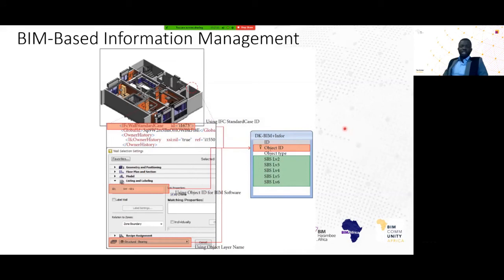The management is achieved by connecting individual information that is being generated here to the individual objects in the BIM model. The construction information database is linked to the BIM model using the space-based categorization codes, which have been generated. Equally, the BIM model object allocated to each categorization code is stored on the database to ensure synchronization, such that we can use the objects on the BIM model to retrieve the information that was carried out to achieve that particular object, or we can use the documented information to retrieve the objects of the BIM model.